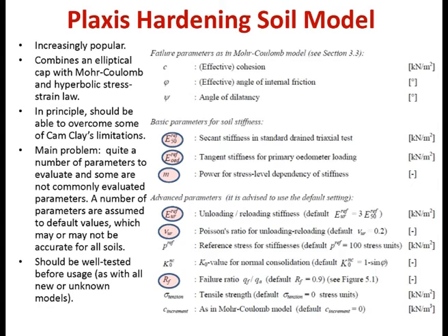The second one is the Plaxis Hardening Soil model. I think many of you are already familiar with it. How many of you have used the Plaxis Hardening Soil model? Basically, to me, one of the biggest advantages of the Plaxis Hardening Soil model is the E50, Eoed, Eur, because they allow you to reflect the non-linear stress-strain behavior of the soil. But none of this will overcome some of the elasticity problem of the Cam-Clay. But you need to get the parameters properly. I think that's the most important thing.